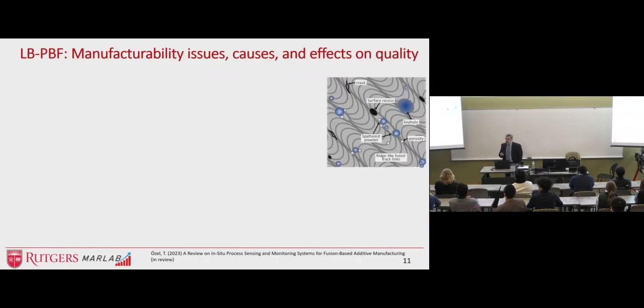So let's look at the type of defects that you can get in laser powder bed fusion. You can get defects such as cracks, surface recesses, keyhole porosity, spatter powder, ridge-like fused track lines. And so you see the track lines. The track is moving this way, then that way, reversing direction, moving back and forth. And then these are the melt pool fronts. So it leaves literally those marks, just like milling marks, where you see a milling tool cutting and then leaving milling marks. But also it leaves a lot of defects, and that's the problem. That is the barrier for metal AM to move forward.